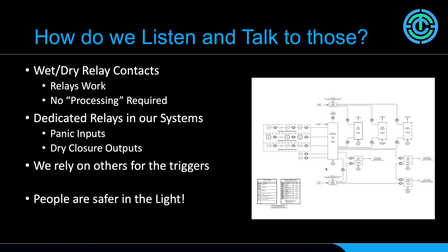They use a lot of just straight dry closures and relays to make things work. They have redundant power supply systems and listed ratings that we'll see in a bit. Most of the interfaces we have to the fire alarm system or the emergency power and UPS backup are a good old-fashioned system of dry contact relays and devices that do not require processing to function. In the event of interference, network failure, or bad programming, we want those things to work, and work every time.